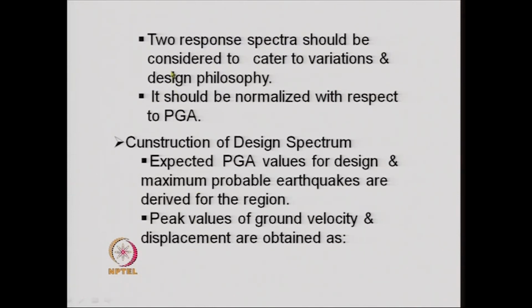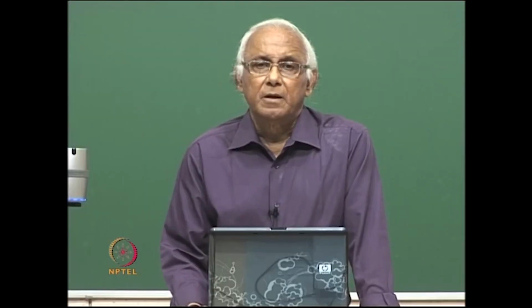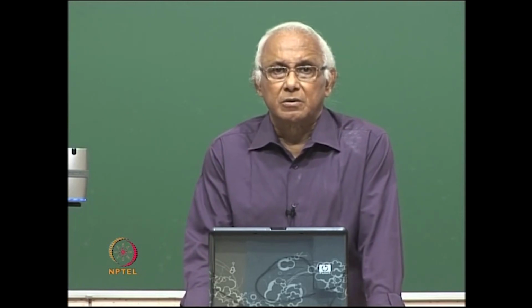Next, two response spectra should be considered to cater to variations in design philosophy. Now, the design philosophy of earthquake resistant design is that we design the structure for a design response spectrum and see that the structure can survive in the extreme earthquake condition.